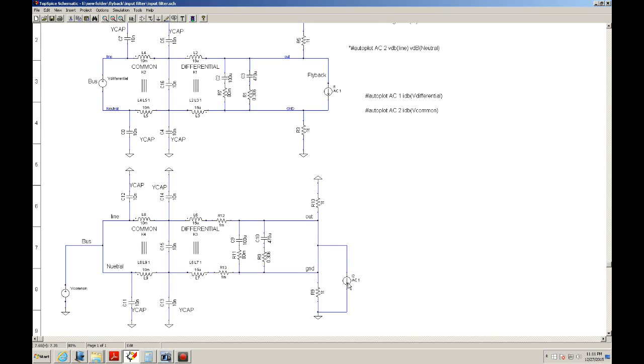I'm adding a signal that is common to both lines, and they travel, and these do not see or do any attenuation of the signal until they actually come to this circuit. Then from there they're summed, and it goes to the bus, through this V common. So I can feed the signal a current source here, and monitor what the current would be at the common. Basically that's what this filter is doing. It's going to be a low pass filter here.